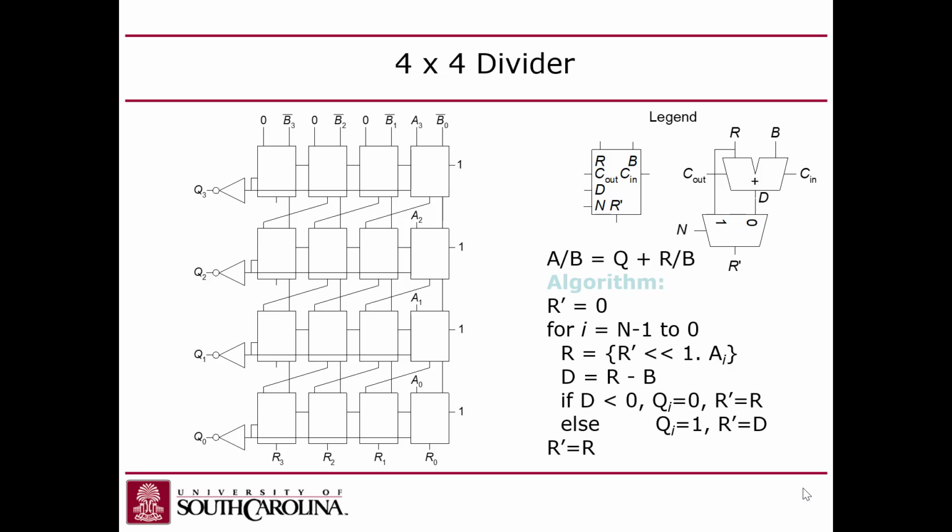So you initialize that remainder register with usually the least significant bit of the original dividend, but the other bits are still in there. They're ready to be shifted in to the right-hand side as you shift that remainder register to the left, right? So you keep shifting that to the left each time, and you try to subtract the divisor from that, and if the result is negative, you restore it.